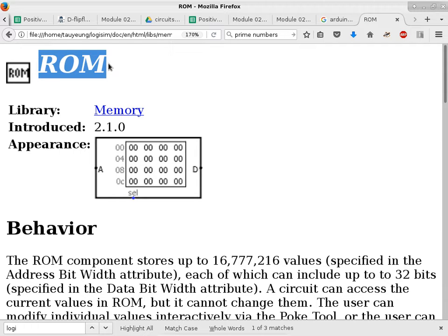What's the practical application of making it read-only, or is that just a limitation of the chip? No, it is an intentional limitation, to use today's term, so that you don't break your device. Yep, because there's a certain core portion of your phone that is not writable. It is only readable. So no matter how much you screw up Android and the whole thing, at least you can get to the part where you can bootstrap again.